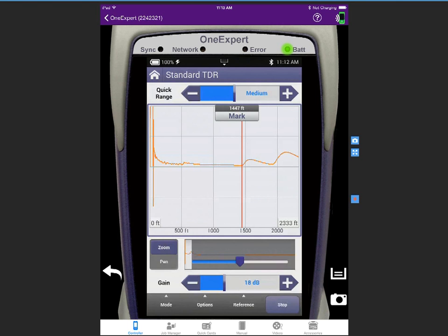Now, that sounds a little peculiar, but for example, a great method of comparison is to compare your faulted pair to a known unfaulted pair. Right? Another method of comparison, a little bit more sophisticated, would be comparing your pair 1 and pair 2 of your bonded DSL service to make sure they were symmetrical or looked the same.